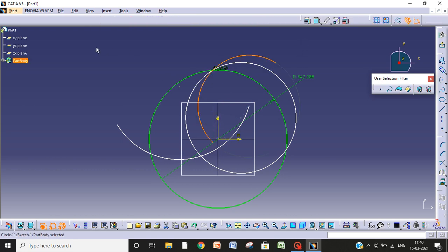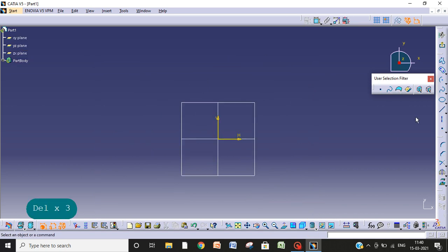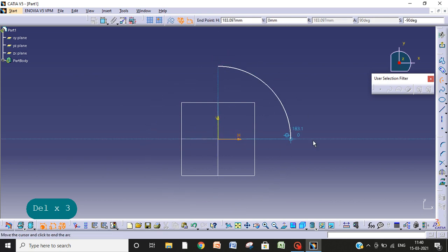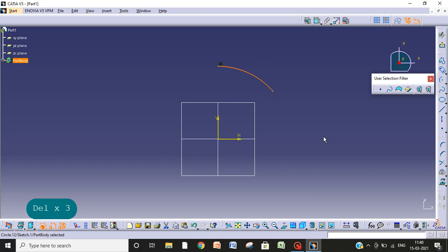Yeah, the last one you may not be getting how I made that. I will delete it. Center arc would be like this. Center, select radius, and then make an arc like this. Okay. We mostly use these commands only. And the tangent circle will be there when there are three lines and one circle tangent to all the three lines. Then this one is our simple line.